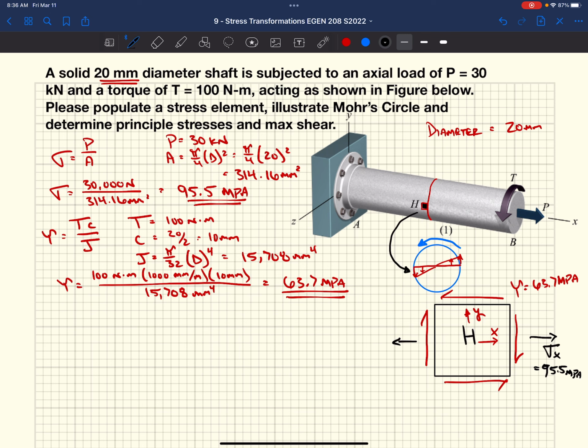And because it's downward on the left-hand side, then if we were to cut this shaft right here and remove all the end material, this torque is still acting right here, right? The torque acts all the way down until it gets taken out at the end. And so you end up with a stress that's acting downward on the right-hand side of this block. Does that make sense?